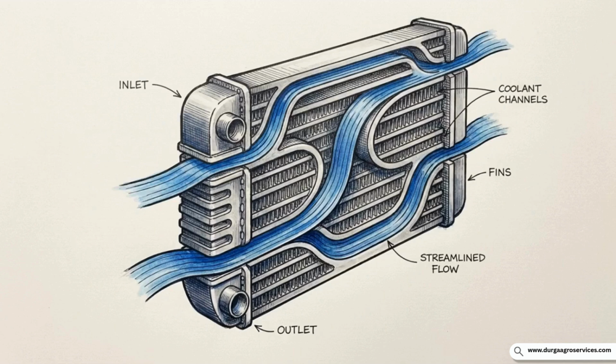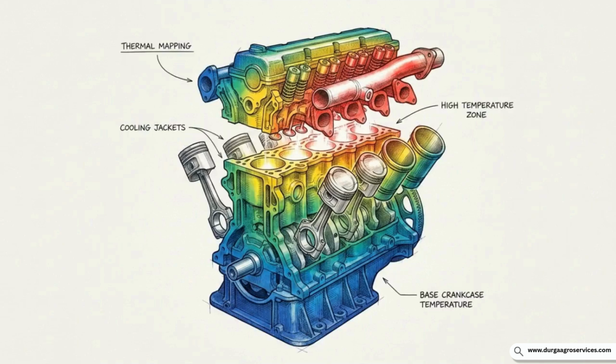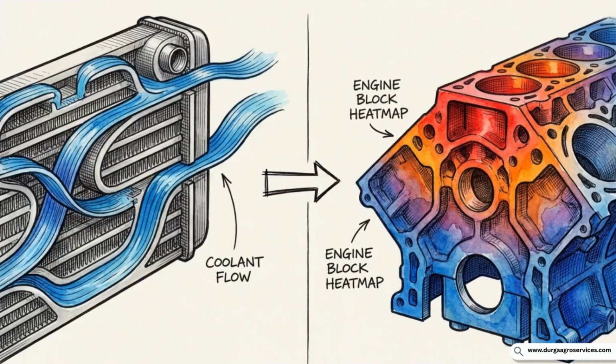By making adjustments to the channel geometry, the particle pathing becomes more streamlined, reducing turbulence and optimizing the overall fluid flow for better energy efficiency. This directly ties into thermal analysis, which evaluates heat transfer and maps temperature distribution across solid components. The fluid data from the CFD study feeds directly into the thermal data.